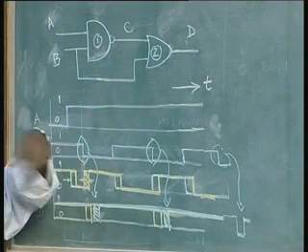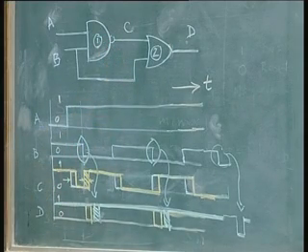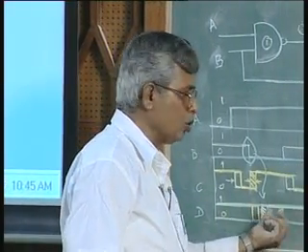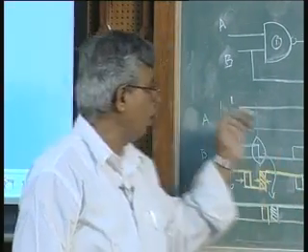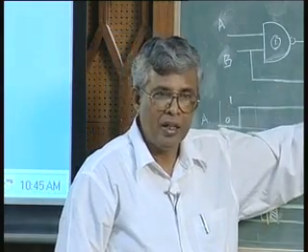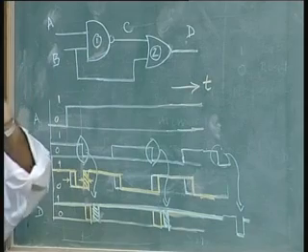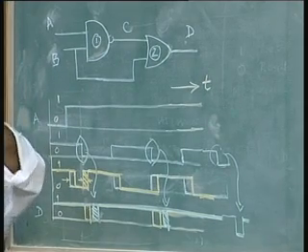We have NAND gates, NOR gates, AND gates, OR gates. By combination of these gates, the idea is to use the delay of a gate, that is all there is to it, nothing else. The delay of a gate is used in order to make the input, even though it is always available at the input of the flip flop, reach the flip flop gates, those NOR gates, which do the flopping operation, only narrowly.